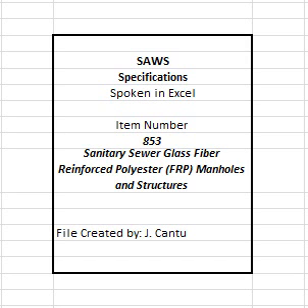2. The lines entering the manhole shall be temporarily plugged with the plugs braced to prevent them from being drawn into the manhole. 3. The plugs shall be installed in the lines beyond drop connections, gas sealing connections, etc. 4. Prior to performing the test, the contractor shall plug lift holes and exterior joints with a non-shrink grout and plug all pipes entering the structure. 5. No grout shall be placed in horizontal joints prior to testing.